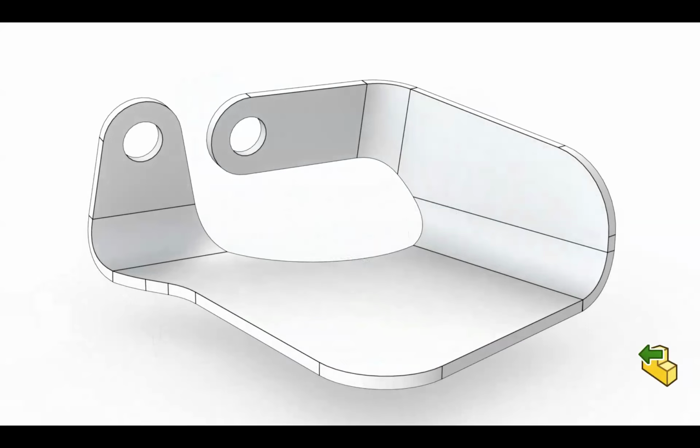You might have something imported, and Creo models are notorious. Their sheet metal does not create continuous radius curvature bends. They're variable radius curvature bends. Not all the time, but often an imported Creo part. So insert bends doesn't work to flatten them. So I'll show you how you could handle something like that if it's imported and you just can't use insert bends. It still won't flatten.